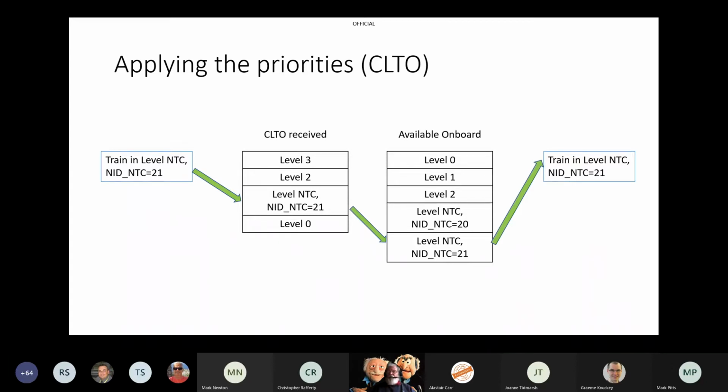So what this allows us to do is at an entry to an area of ETCS with line side signals and TPWS is for the driver's entry of the level to determine whether the train transitions to level 2 or remains with TPWS as the protection system.